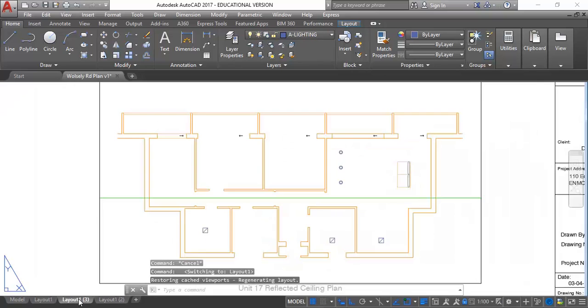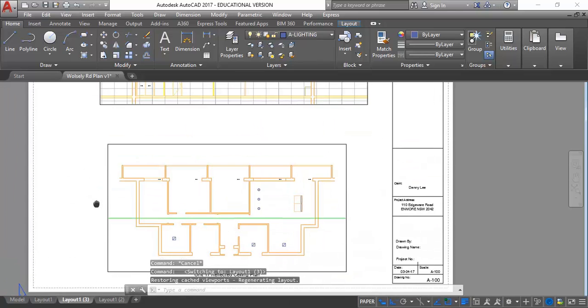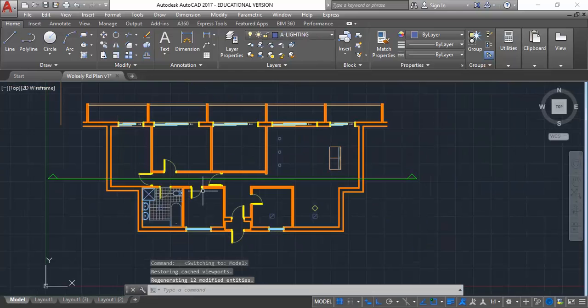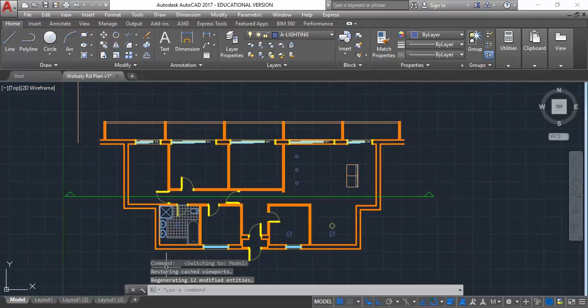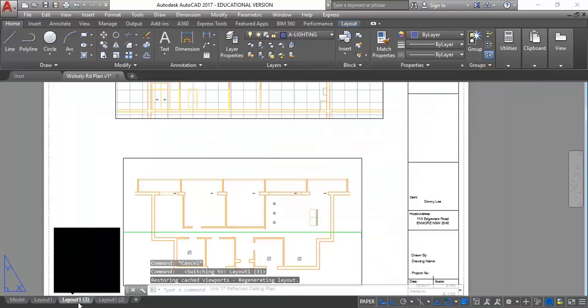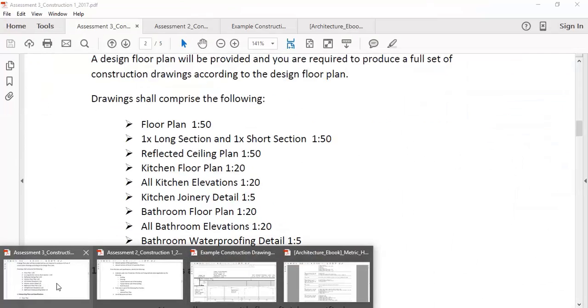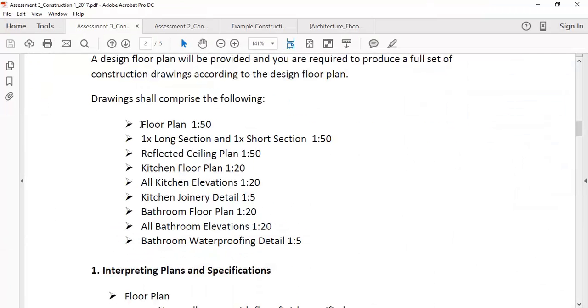So can you see there how you can get multiple drawings out of the one drawing essentially? I've got this one drawing back in the model, it's got all these different things, but by using combinations of layers differently in the viewports, I can achieve these different drawings, the floor plan and the reflected ceiling plan, from one drawing, which should make it less work for you.